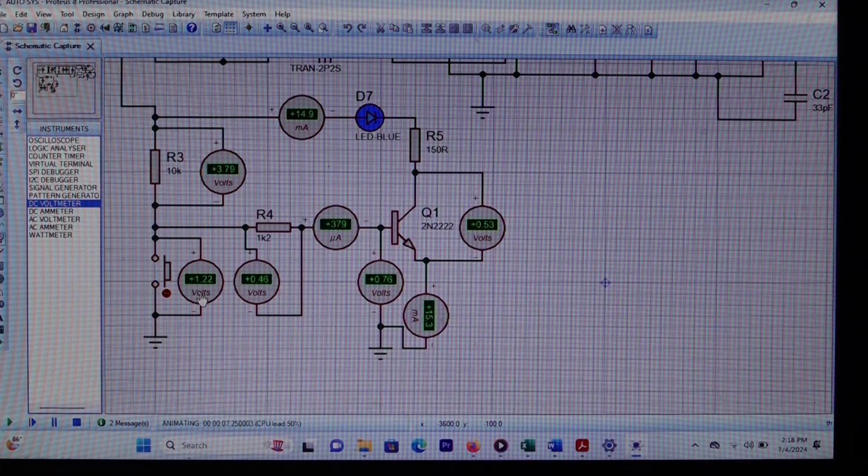We expected 5 volt or 5.01 volt, right? But because we have interconnected 2 blocks, in simulation you experience a voltage drop from 5.01 volt down to 1.22 volt. You have to take note.